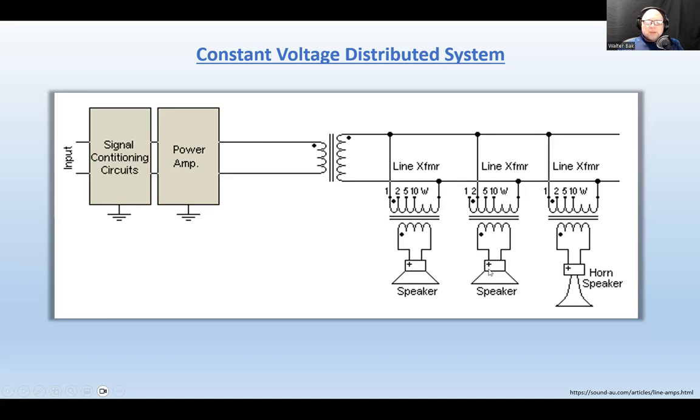If this speaker is in phase with that one, both membranes are going to push out during the vibrations that make sound. Now, if you connect them the opposite, yes, they're going to make sound, but if one is going to push, the other one is going to retract.